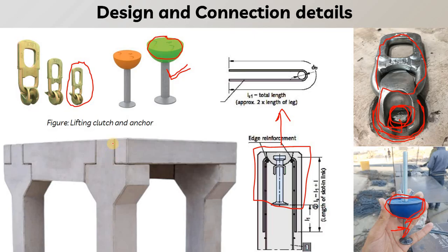So now here you can see a clear picture in which we have the corbel connection. This is the corbel on both of the ends here, and we have the precast beam over here. So this is our precast beam. From the corbel there will be reinforcement that will be projected out on both sides, and we will have the dowel tube over here which will be connected, and concrete or special grouting material will be filled in this tube to connect this element.